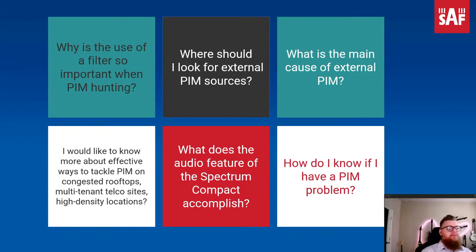It could also be something near field, which is what you're using the near field probe for. It could also be something far field as well, something that you're not in control of in the environment past your site. I know that was kind of a convoluted answer, but it could be anywhere, honestly, anywhere on the site and anywhere surrounding where the signal is touching.